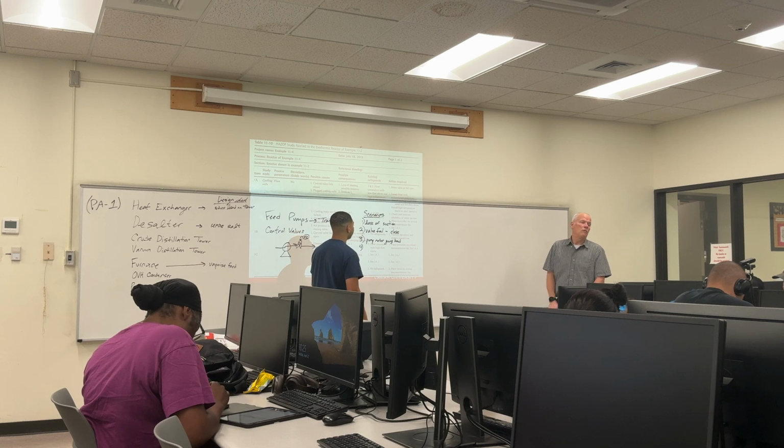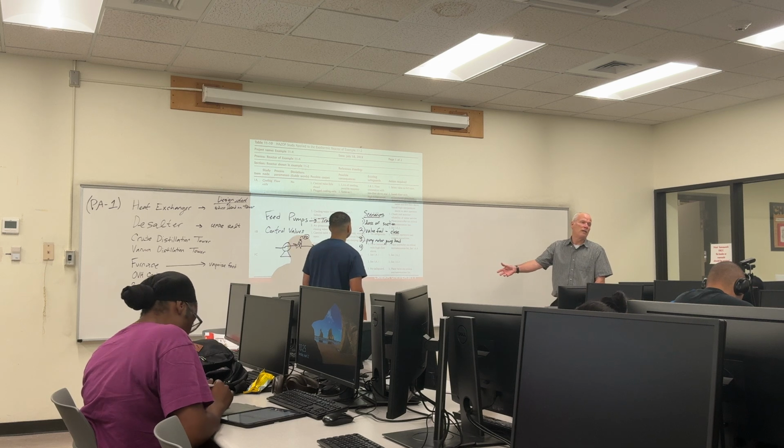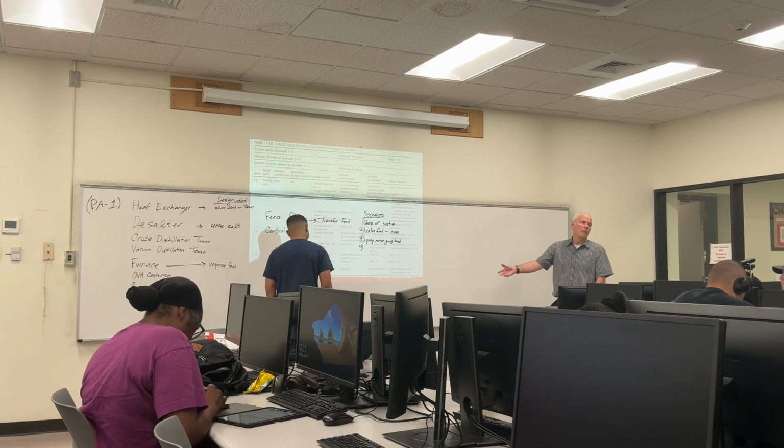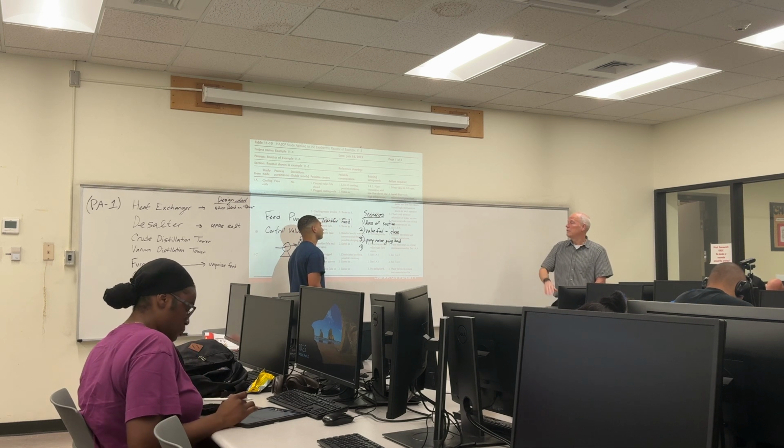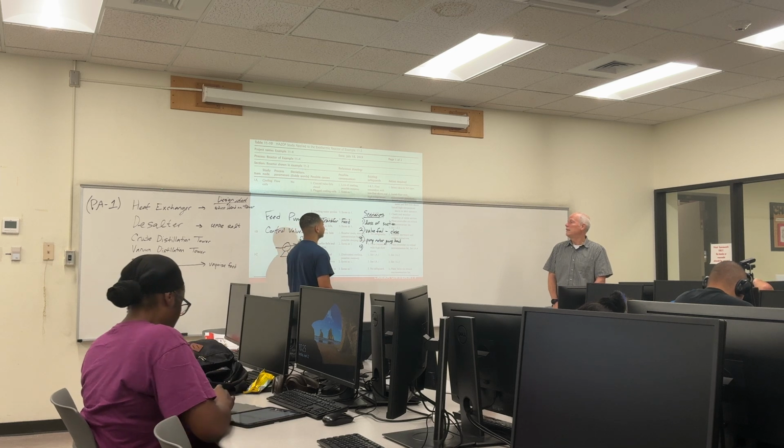There are two different reasons. One, it could be a fail close valve. Loss of instrument air. Yeah, so if it's a fail close valve, it could be instrument air loss that did it. Or you can always fail close a valve if you say the controller failed close. Okay? You can always say that.